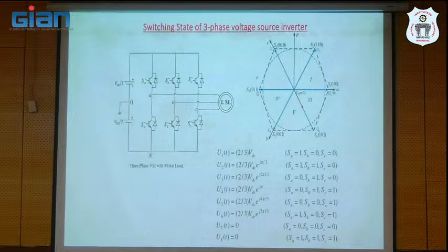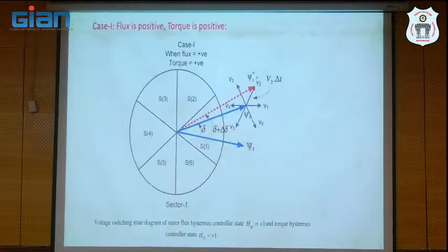Based on the hysteresis states, we can identify whether we need to accelerate or decelerate the torque, or accelerate or decelerate the flux in the next coming instant. It will be decided by your hysteresis states. Based on the hysteresis state, you have to write the predefined lookup table, right? Whenever you want to develop a lookup table, this is what they are doing.